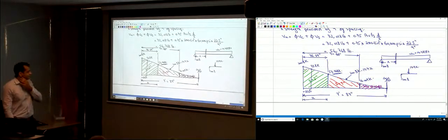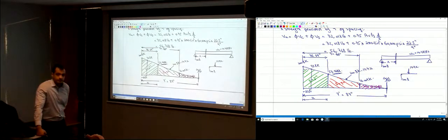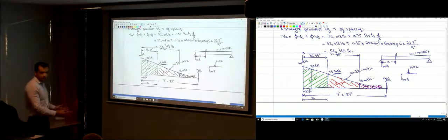So, the stirrups don't really affect the strength against bending moment. The stirrups don't have an effect on the strength for the bending moment. But if you use the non-conservative equation for finding V_c, the strength of the concrete depends on the bending moment, because you have a term that has the moment. But we're not using that here.